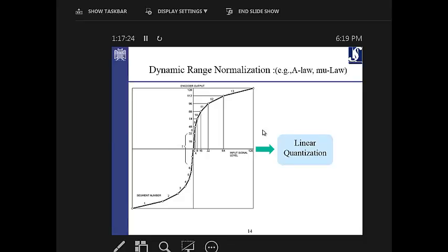So when we use such an exponential form of dynamic range normalizer, what we are inherently doing, implicitly, is saying that part of the signal is more important than the other part. So the lower amplitudes are more important. Here in the lower amplitudes, we are actually linearly changing in this dynamic range compression. But when we are, for example, above the 16 dB level, we see that it's actually saturating. It means that above this level, in the dynamic range, normally you don't have that much important information.